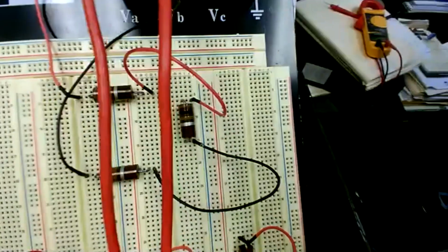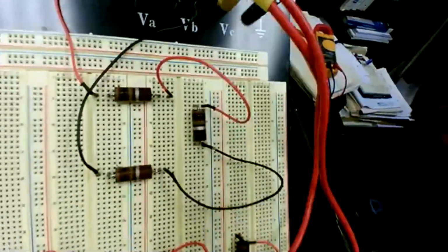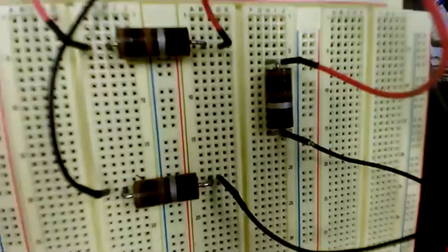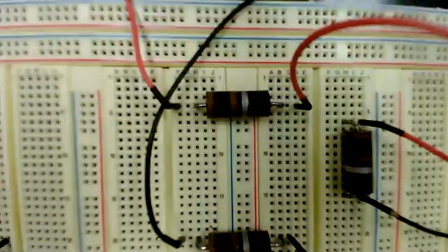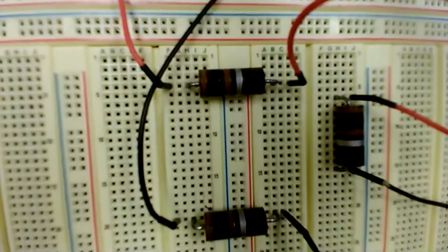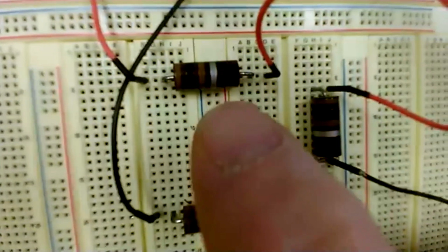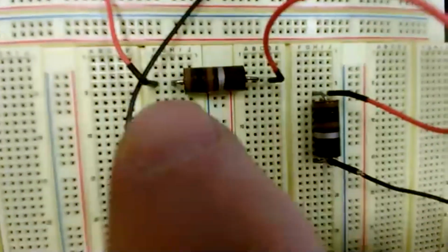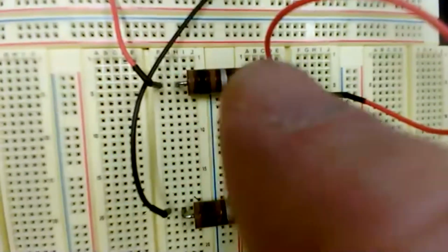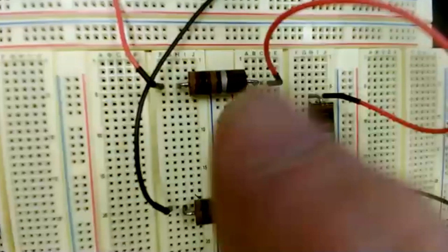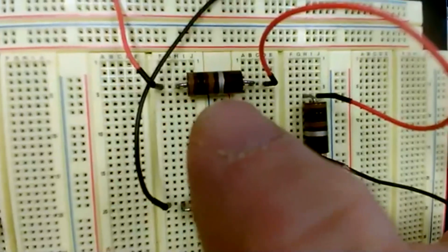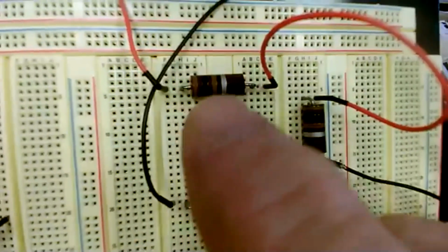Now, that's a close up of what I've got there. When you open your email and you get the color code chart out of there, you calculate what it means when you have a brown stripe and a black stripe and a brown. It's brown, black, brown with a tolerance of silver, which means 10%. The brown means 1, the black means 0, and the third one is a multiplier that you multiply by 10. So if you have a 1 and a 0 and you multiply by 10, it means 100. And that chart, when you look at that chart, that's what it means.